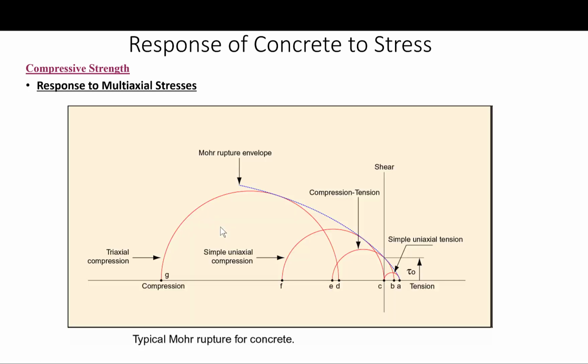Okay, so for the behavior of concrete under shear stress, pure shear is not really encountered in concrete structures. However, an element may be subject to the simultaneous action of compressive, tensile, and shear stress. So the failure analysis under multi-axial stresses is carried out from a phenomenological rather than material standpoint.